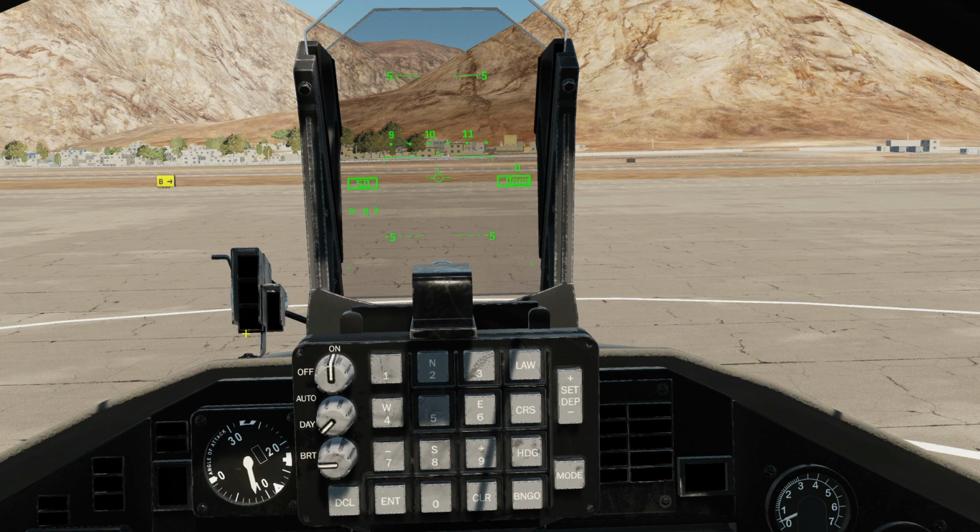The angle of attack indexer is a series of 3 lights, whose combination shows how to get us on speed and on the correct angle of attack for landing. Next, the HUD will change slightly depending on which mode you're in, but in its base mode we have a roll indicator along the bottom here, sorry that we can't see it very well. We have a pitch ladder: -5 degrees, horizon line, +5 degrees, +10 degrees, and so on.